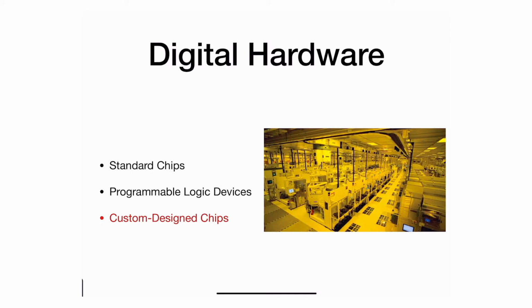However, if you have the capability to use it, you're going to see that the chip you design could be very, very small, and also very low power. Compared to FPGAs or programmable logic devices, you'll gain a lot more power efficiency, and it's probably much smaller. So FPGAs give you flexibility, but consume a little bit more power and space, while custom logic consumes less power, potentially, depending on the design, and also less space. But again, it's only economical if you're producing it on a very large scale.